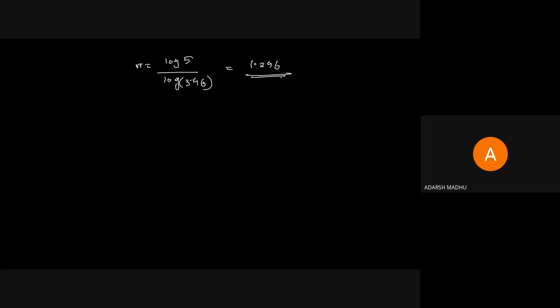the increase in internal energy. The increase in internal energy, delta U, is what we are finding. The third one. Delta U, that is m cv (T2 minus T1), right? We know the value of delta U equal to m cv (T2 minus T1), or U2 minus U1. When m equal to 1, cv T2 equal to U2 and cv T1 equal to U1, that is U2 minus U1. So that is m cv (T2 minus T1). The mass we know.